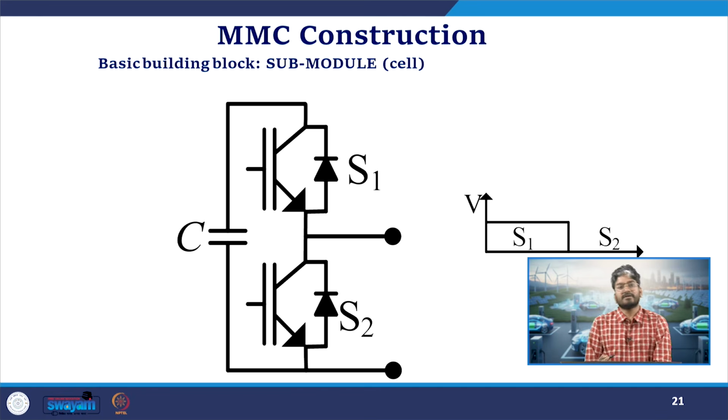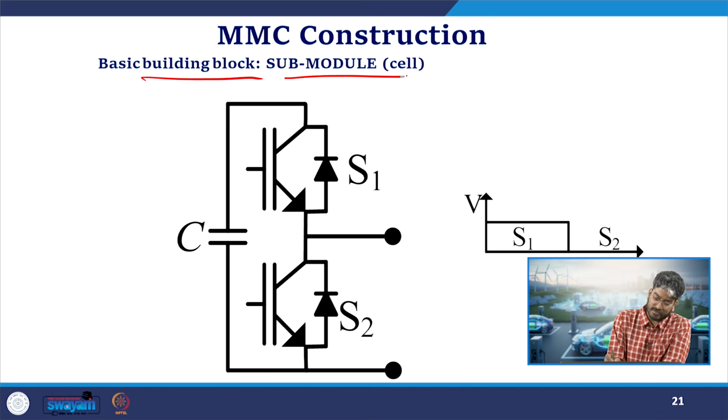Now let us see the working of this. Before that, we will see the basic building block, that is our submodule or cell. Sometimes it is called a cell or a submodule. The submodule is the component which is the building block of the circuit. I can just repeat n number of submodules to construct an n plus 1 level MMC.